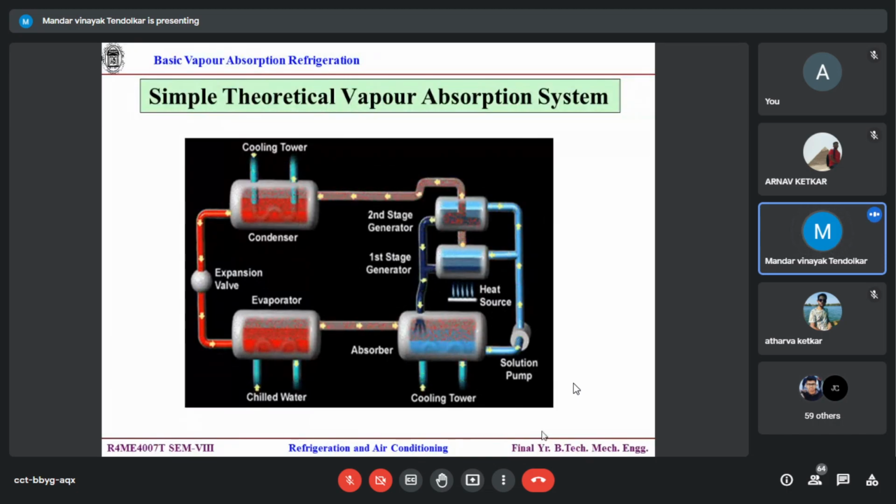The vapor part, the refrigerant, red color, is going out. So the second stage generator is basically the dephlegmator, and in between the generator and the dephlegmator is my rectifying column with those plates. That is why I have selected this animation, because the arrow diagram and everything is very clearly self-explanatory.